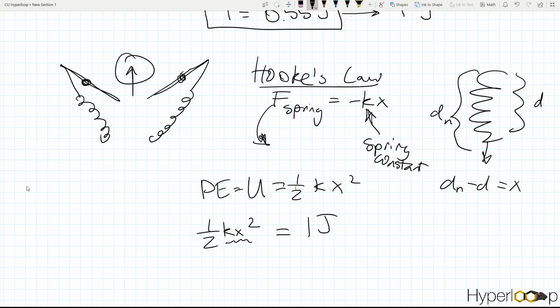Now you'll notice that we have these 2 variables here, and I've drawn this diagram out, but what I can tell you is that when you build your shooting mechanism, if you're using springs, then you'll be able to estimate what your x will be to figure out what your k needs to be, and then you just iterate back and forth, bouncing between your k's and x's until you arrive at a combination that works for you.